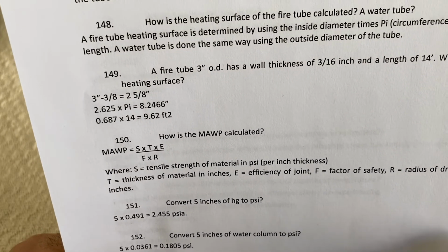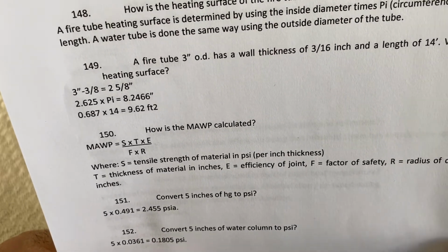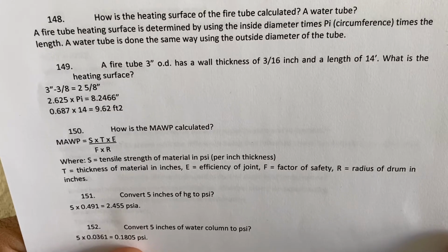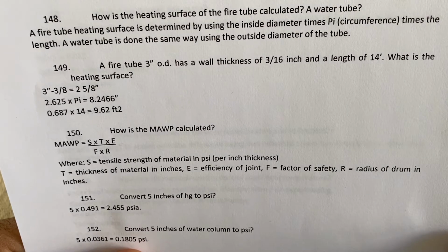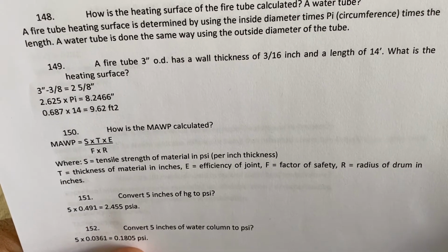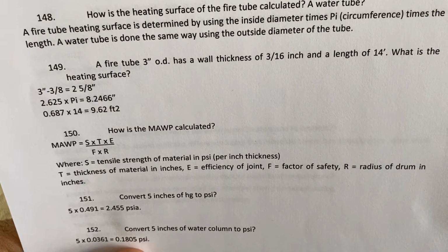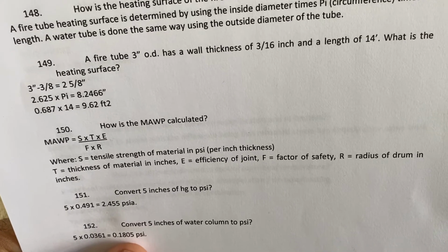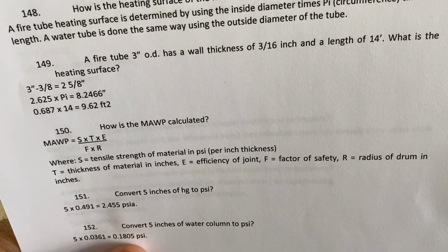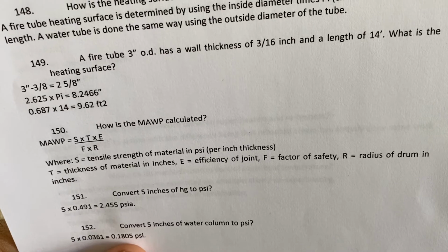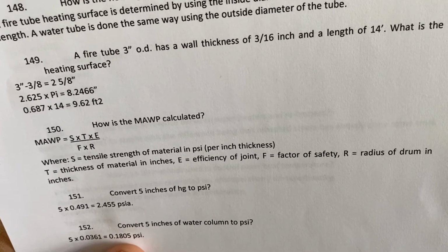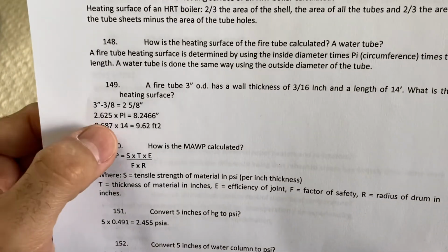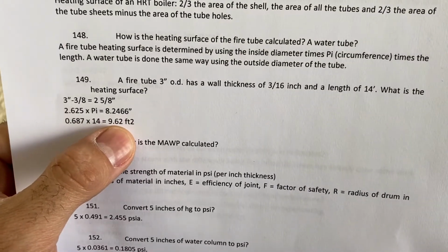And the 2 5/8 times pi, okay? Now, don't forget, the inside diameter is in inches, and the length is in feet. So you need to transfer inches to feet, and then feet times feet. Because, remember, another rule of the heating surface. I'm going to say that again to make sure everybody understands. Parts of the boiler with water on one side, products of combustion on the other side. Always measured by the side receiving heat and always in square feet. So that's why we change inches to square feet, to give you the heating surface in square feet.